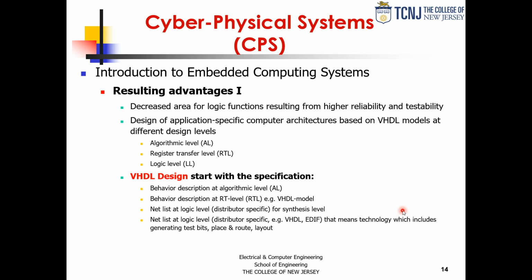If you're going to be mapping something to an FPGA, obviously you don't know some of the physical aspects of that implementation because you're going to map it to a new FPGA, maybe combine a block that somebody else designed and add it to your design, synthesizing the whole thing together and coming up with a new design. But the fact that you can reuse a block, that's important. So try to design at the highest level of abstraction and reuse as much as possible.